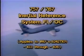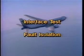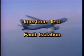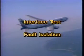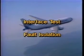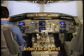This presentation provides an introduction to the Inertial Reference System interface test procedures and indications. We will also cover fault isolation, which includes built-in-test-detected faults, manual fault isolation, and IRU rejection criteria. The IRS interface test is a quick test to check out airplane interface integrity.